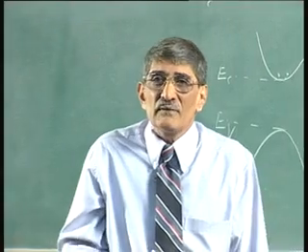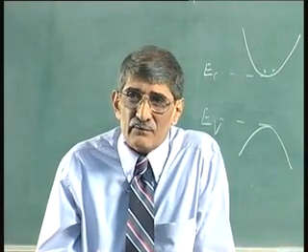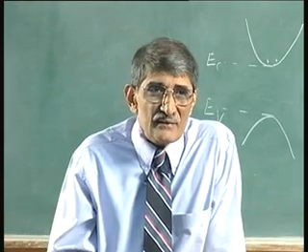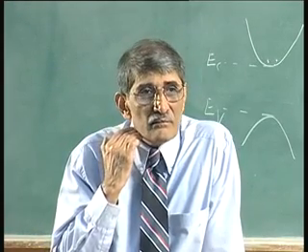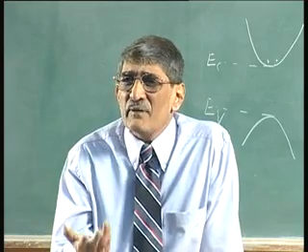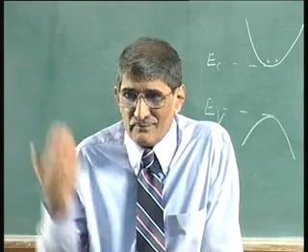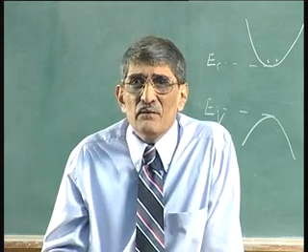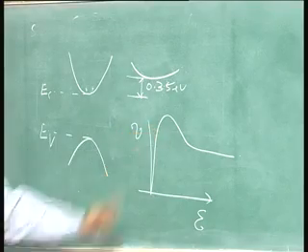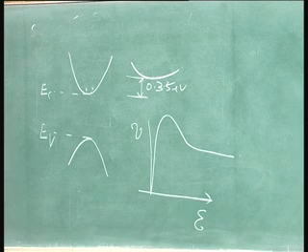Okay. So, in devices which have 0.3 microns and 0.3 volts, you will have high fields, high velocities, because there is no intra-valley scattering. Even if you have 1 micron channel length, you get just about here. Okay, this is just incidental.